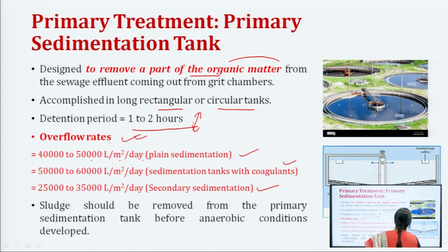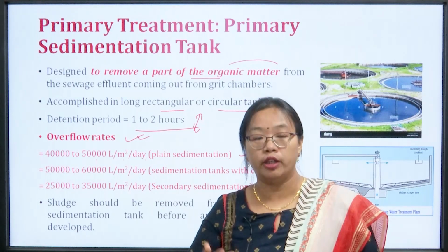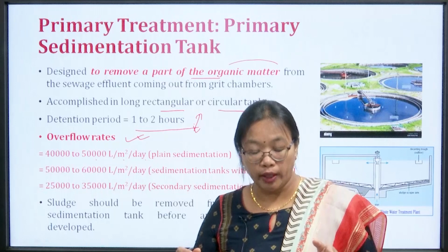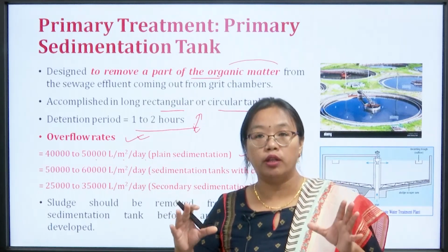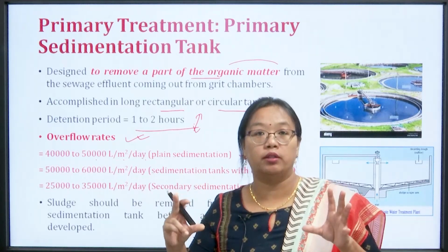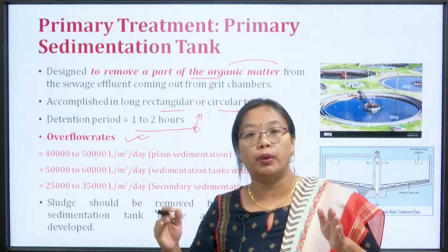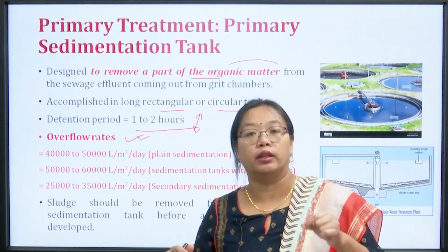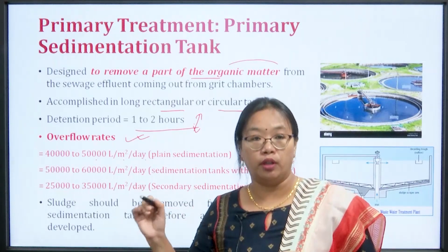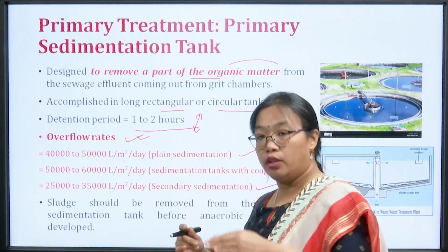I think you have already talked about sedimentation tanks in water treatment, and the principle behind it is similar. In a sedimentation tank, you are holding the wastewater for the detention period so that all the settleable material settles down, and afterwards you allow the effluent to leave. Whatever is left, the sludge, is going to be removed.